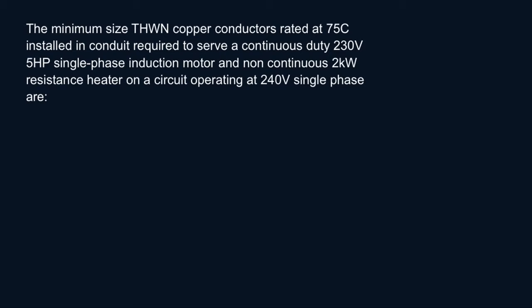So this problem is asking for the minimum size of copper conductor that's required to serve two loads. One is a single phase 5 horsepower induction motor, continuous duty, 230 volt, and the other load is a heater, non-continuous, operating single phase still, 240 volt. So the question is asking for the size of the conductor.